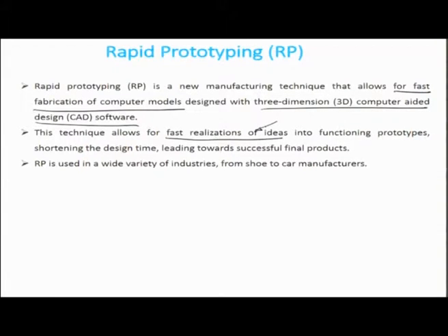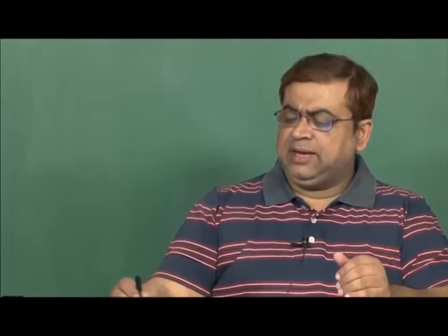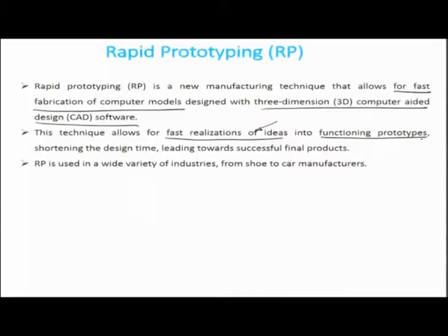Particularly it is used more as a modeling tool for the prototyping stage of the design. Most designers are habituated to visualizing 3D shapes, forms, etc. by looking at rapid prototyping forms because it's easily doable. So basically the idea here is that through a polymer or through metals you can actually do layer by layer manufacturing, so that any complex topology, any complex shape can be reproduced. And turning ideas into functional prototypes is the aspect of design which is covered using these rapid prototyping techniques.